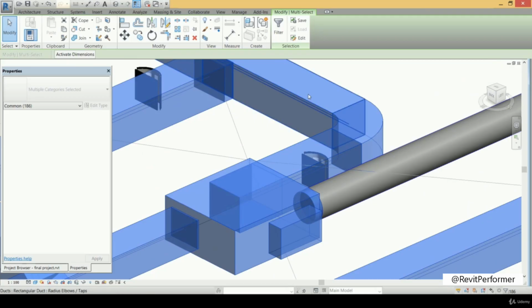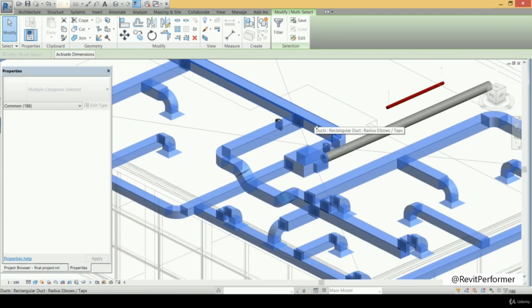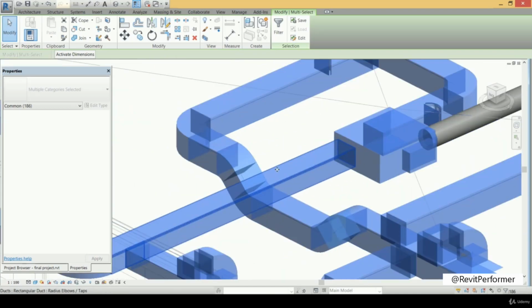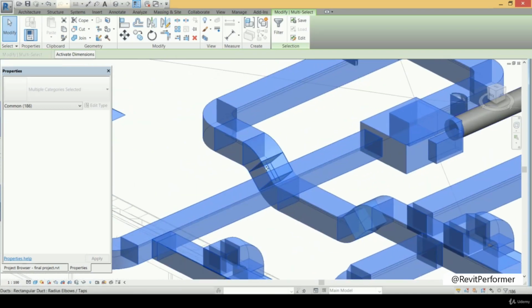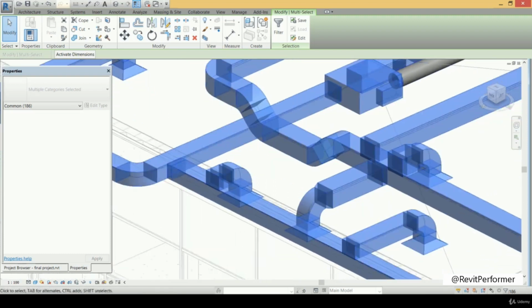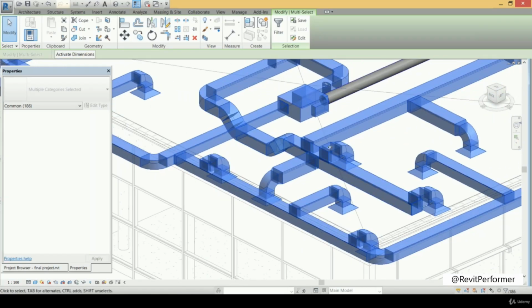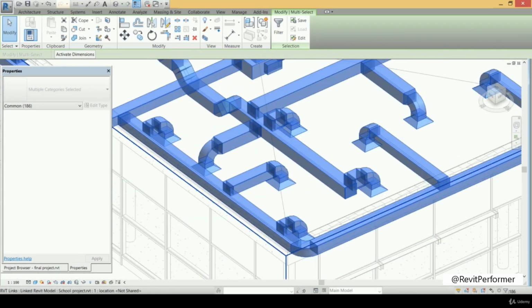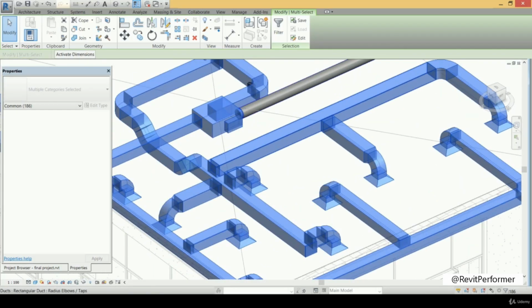So this is the return air duct that we had just created from the previous tutorial, and this is a branch from it, and this is the trick that we have made, which is to change the offset of the return duct to overcome the interference with the supplying duct. And then we go there with that return duct to feed that air terminal and that second one. And here, if we go there a little bit, we find that we have also that branch duct to feed